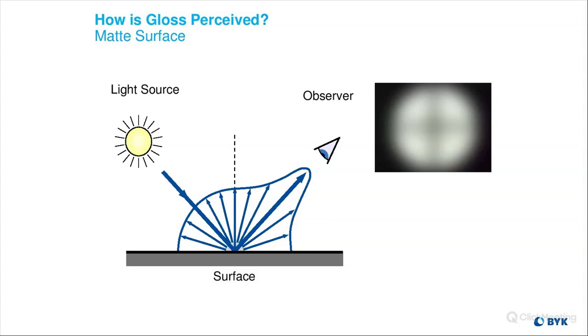And so you don't have to risk getting the instrument covered in material, because it takes the measurement non-contact. It's roughly about 0.2 millimeters off of the surface. It has sensors that detect how close it is to make sure each of those measurements is always going to be the same no matter what. So that's another good option if you're testing wet surfaces, a good non-contact method. Great solution if you want to get into the robotic stuff.